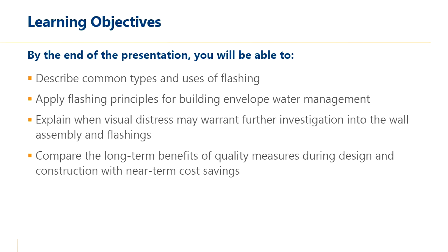All right, so the goals of this presentation are that by the end of today, you will be able to describe common types and uses of flashings, apply flashing principles for building envelope management, water management in general, explain when visual distress may warrant further investigation into the wall assembly and its flashings, and compare the long-term benefits of quality measures during design and construction with the near-term cost savings of maybe omitting some of those QA, QC elements.